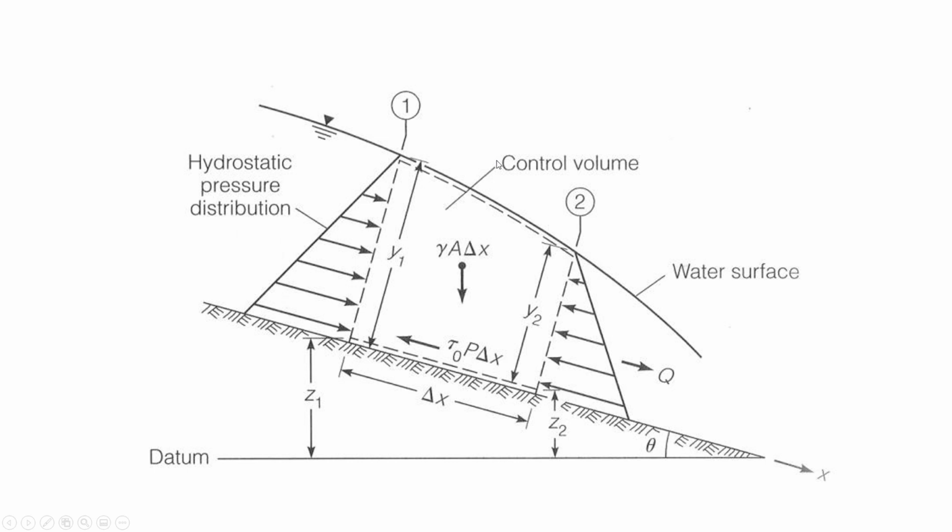In a closed conduit pipe, water can flow uphill if it's an enclosed pipe because of pressure effects. But when it's open channel flow, water can flow uphill just for a brief moment, if it's got some momentum, like there are water parks where you'll be on the water slide and it goes uphill briefly, but not for very long. But let's just say that water is going from the left to the right, and you can see that it's getting shallower as you go downstream.